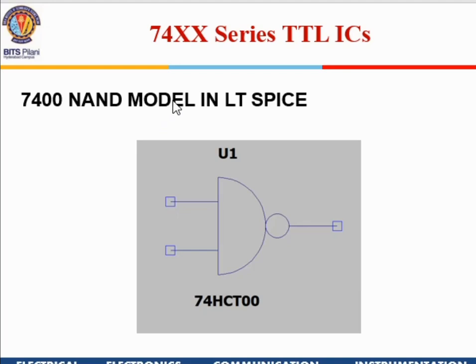And 7400 is a quad NAND gate, but in the model, when we pick it up, it will pick up each gate separately. Otherwise, every time you click on a 7400, if it gives me 4 NAND gates and I just require 1 NAND gate, the circuit will look clumsy. But in a practical circuit, even if you want to use only a single NAND gate, if you are going to design a PCB, you might have to use a 74 IC and leave the three NAND gates blank without any connection, right?